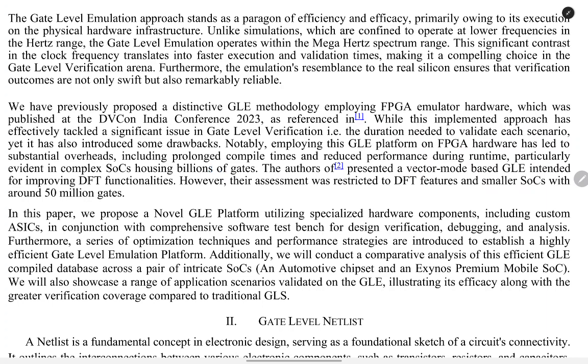The authors presented a vector mode-based GLE intended for improving the DFT functionality. However, their assessment was restricted to DFT features and smaller SoCs within around 50 million gates. In this paper, we propose a novel GLE platform utilizing specialized hardware components, including custom ASICs, in conjunction with a comprehensive software test bench for design verification, debugging, and analysis. Furthermore, a series of optimization techniques and performance strategies are introduced to establish a highly efficient gate-level emulation platform.